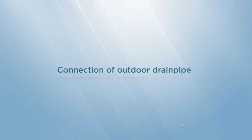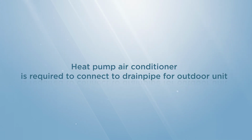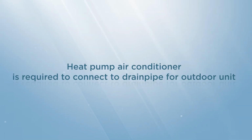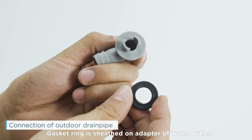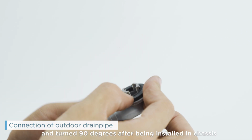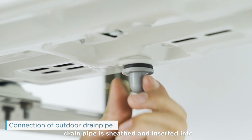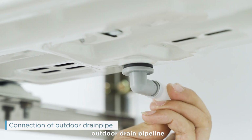Connection of outdoor drain pipe. Heat pump air conditioner is required to connect a drain pipe for the outdoor unit. Gasket ring is sheathed on the adapter of the water outlet and turned 90 degrees after being installed in the chassis through the bottom of the outdoor unit. Drain pipe is sheathed and inserted into the outdoor drain pipeline.